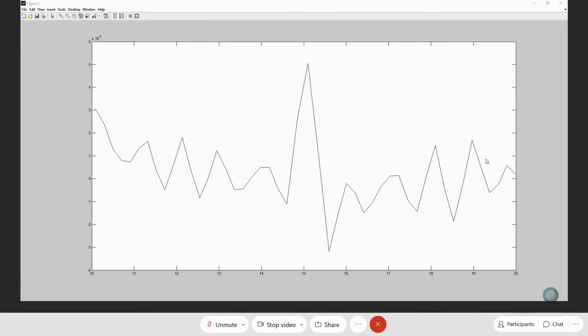But instead of a nice smooth plot, what we see essentially is noise. And the reason we see noise is because of ODE45. ODE45 is just an approximation to the solution, right? It computes a pretty accurate solution, but it does introduce small errors each time it makes a step. So what you see is not the true difference between the solution and this simple harmonic. It is that plus errors that come from ODE45. And these errors overwhelm the computation in this case.